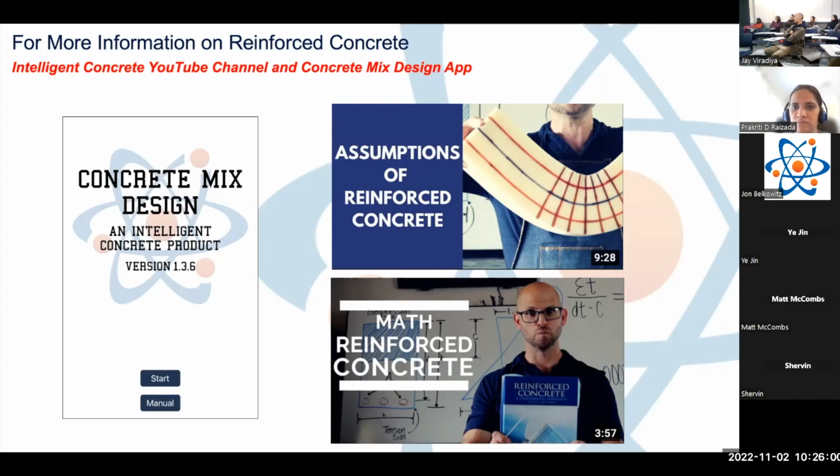When we lose our steel, when our tension zone fails, it doesn't mean the concrete ultimately falls into the ocean. The concrete can still be there, but ultimately, if we lose our tension zone, when the load to cause failure creates that failure scenario, we don't have a tension failure. The failure is monopolized by the concrete. And we all know concrete is horrible in tension. So the concrete cracks, there's no steel to take on that tension load, and we have that catastrophic failure.